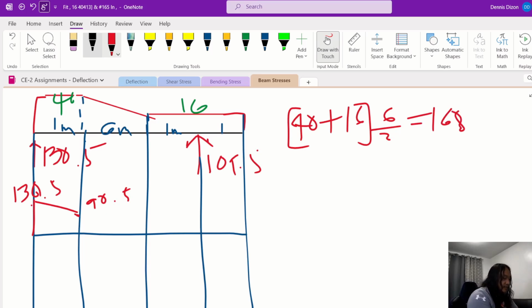So again, this is now a second degree curve. This is minus 77.5. And then from there, you subtract another uniform load, which is 16. So minus 77.5 minus 16 is, now this is a first degree curve, or a straight diagonal line, because the load is a 0 degree, so this is first degree.